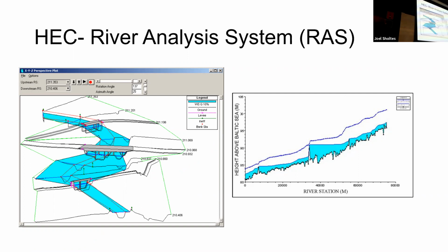And if you look at the profile, then you can see what the water surface elevation is for different flow rates. This might be a lower flow rate, a higher flow rate. And here is what that is in this kind of oblique view, where we're tying the water surface elevation into these cross-sections. And then these cross-sections also have X, Y, Z coordinates in space. It's a little hard to wrap your head around how this is one-dimensional, but there's a one-dimensional value here, and then we kind of extrapolate that into space, right? I'll show you some other examples of that when we do the walkthrough.